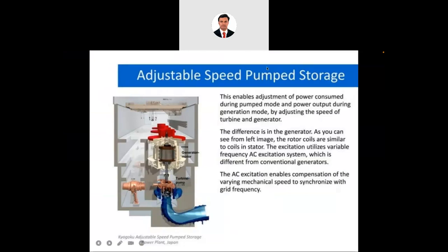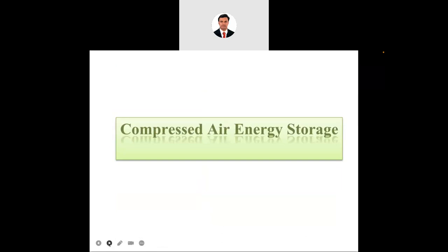So that is about the pumped storage type of power plant. Okay. So similarly, another power plant is used to store energy. That is known as compressed air energy storage. Similar to the pumped storage power plant, we are using the energy to compress the air, and we store that compressed air in one particular vessel or below the earth.